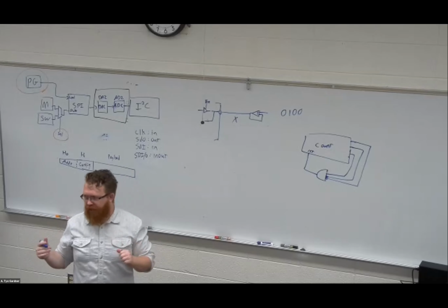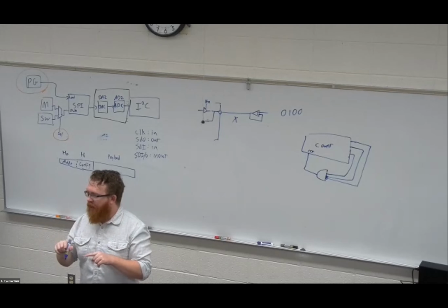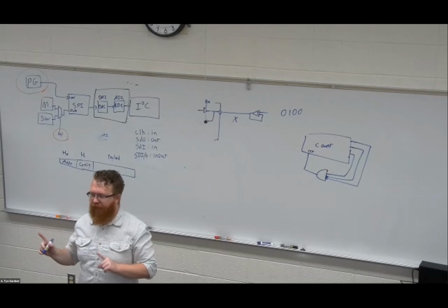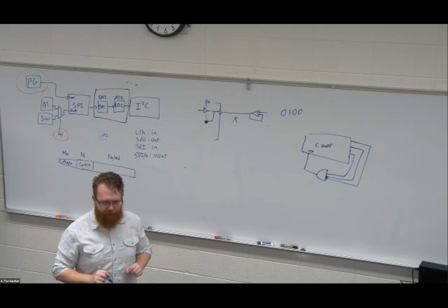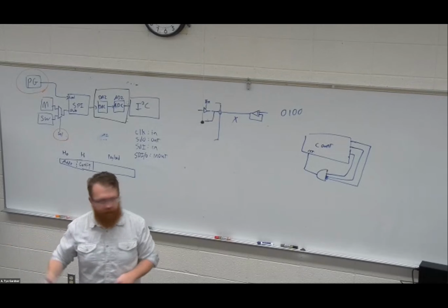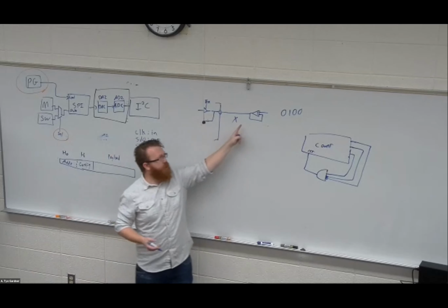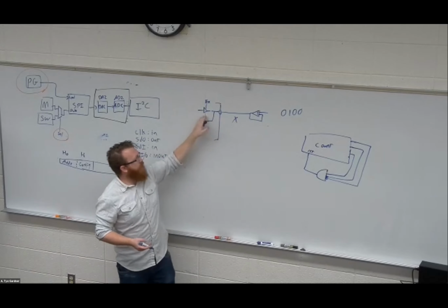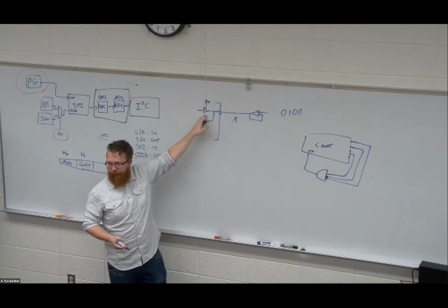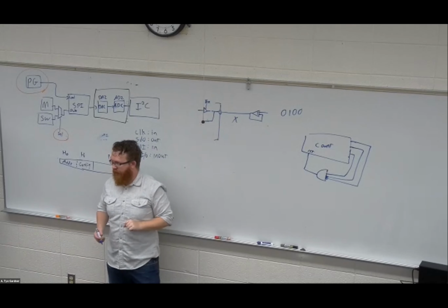And worse, since you're interfacing to the real world instead of inside of the FPGA, when that conflict happens, it can actually break your FPGA I/O pin because it's trying to source enough voltage from here to make it 0, for example, and this is driving a 1. So if this one's overcurrent protection fails, you break your device.